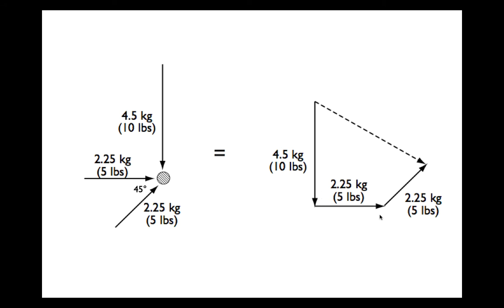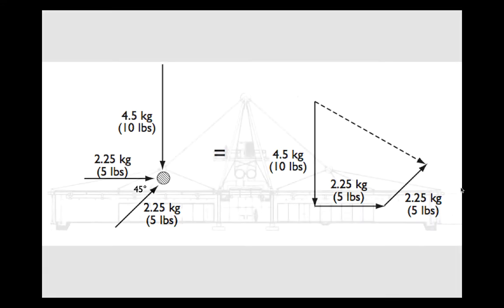Vector geometry allows us to sum these up. It allows us to come up with a kind of resultant. And then remember, if we flip that resultant around, that's the structural engineer's job. That's what we have to find. We have to find a force that is this magnitude, this direction, but the opposite sense, so that we have an equal and opposite force working on that free body. And when we do that, what we'll find is that the force based on the resultant will keep the body in equilibrium against all of those three forces, right?